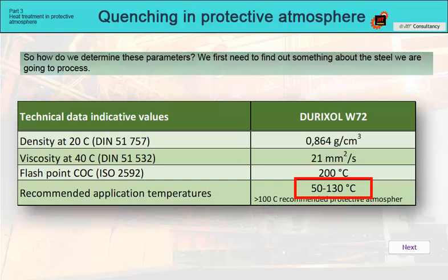We will choose the temperature of the oil bath according to the characteristics of the parts and the possibilities of the oil. Since we want low deformations, we will increase the oil temperature to 120 Celsius, and we will also prescribe the oil agitation mode, its speed, or possibly the direction of flow. So we now have all the necessary heat treatment parameters. The carbon potential will therefore be 0.9, the quenching temperature 820 Celsius, and the oil bath temperature 120 Celsius.